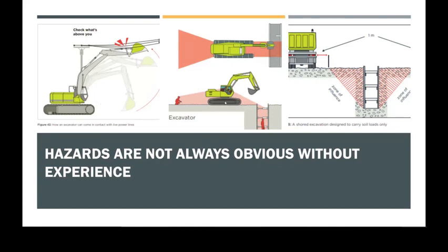So the other thing is the swing radius of the boom and the back of the digger. It's important that you're visible, and I'd really stay out of the way of the swing rotation of that digger. So if you need to talk to the digger guy, one, you should have high vis on, hard hat if you're working around mechanical equipment like that.